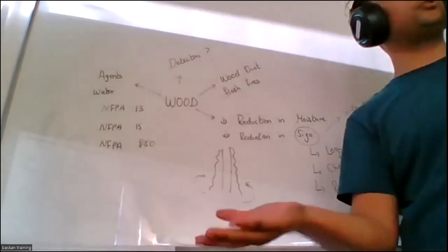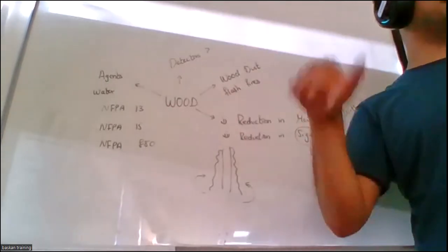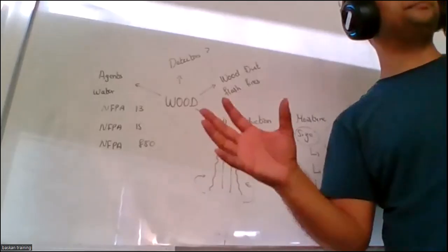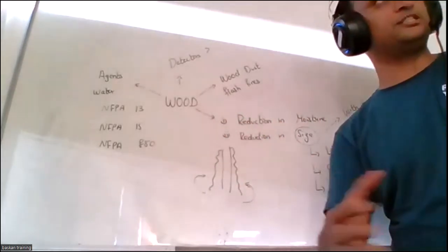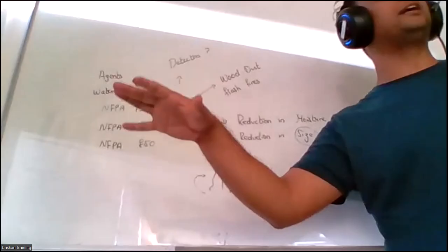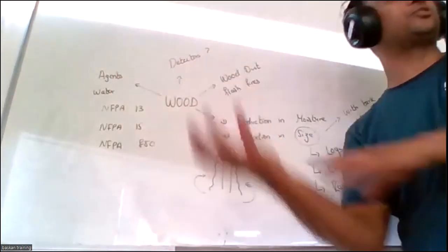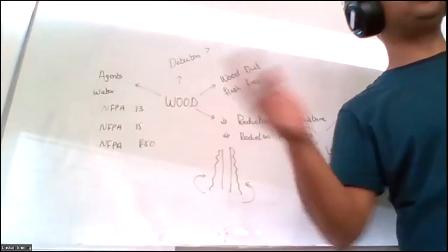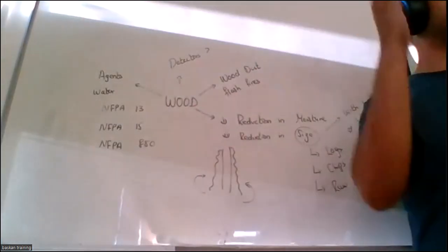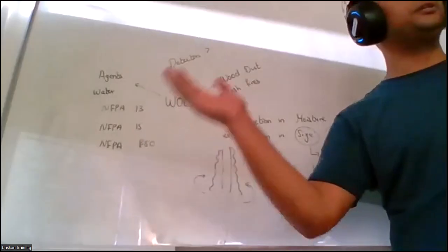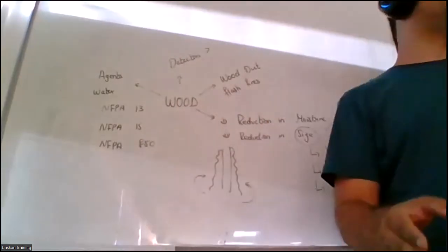Dust from the source doesn't have a pattern; whenever it rises, it will always rise in a random pattern. Smoke has a specific pattern from the source, so that is how it differentiates. It has an algorithm that can differentiate between the smoke particulates and the wood dust based on the release pattern.